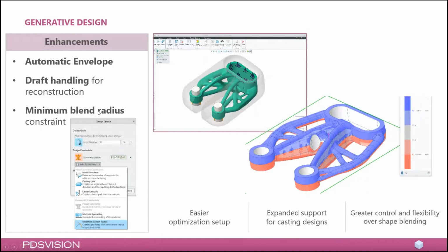Then you have a second one called minimum bend radius, which simply means that if you think about, let's say, a milling tool, you have a minimum radius for the milling cutter size, so that you don't get too small geometries. That also enables you to control how small the details are, since the minimum radius will otherwise be violated. So if you want very tender structures, like needles, you have a smaller radius, but a bit bigger one if you have more of a beam or slab structure. So that is also driving the generation of the model.